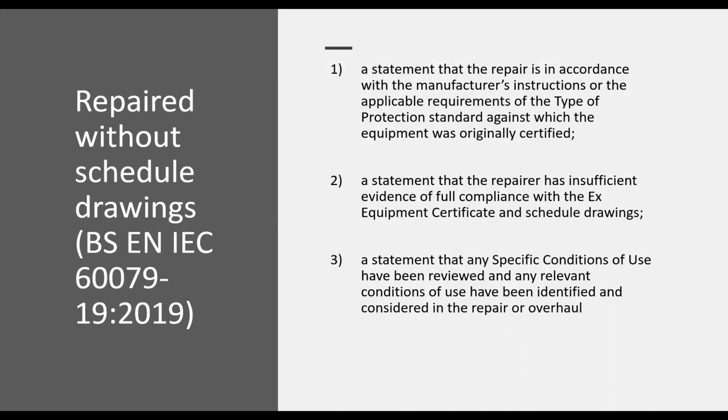Okay, and that all the special conditions of use have been reviewed. Special conditions of use are explained, or you know that the special conditions of use, when you look at the certificate number, it will have an X at the end. Those special conditions need to be looked at to see if they are relevant to any of the EX protection. For example, flame paths.